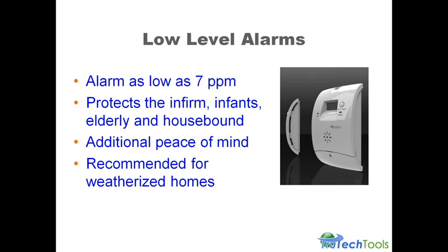And typically, if you have somebody that's sick in the house, an infant in the house, an elderly person in the house, somebody that's housebound, kids, these are people that aren't going to be as tolerant to low levels of CO in the house as a healthy adult would. Got to remember, all the CO testing we've done has been done on military people. I think they're probably in a little better shape than most of us are. They're going to have better lung capacity. They're working out. They're in good shape. Most of us aren't in good shape, so most of us aren't going to be able to survive as well in higher CO as somebody like that would.